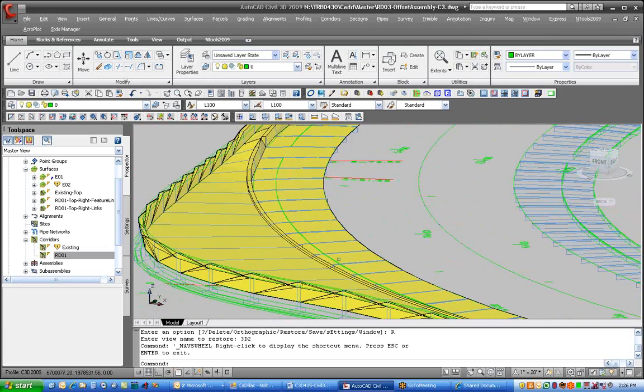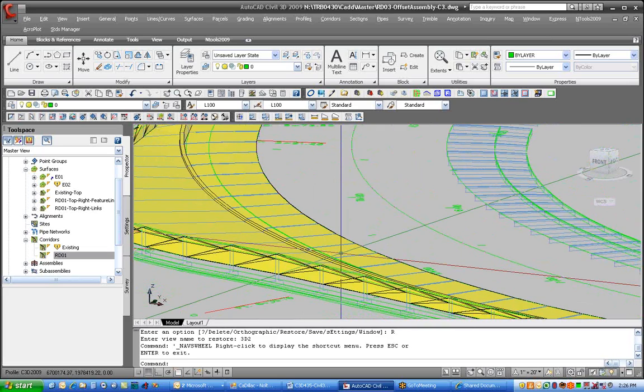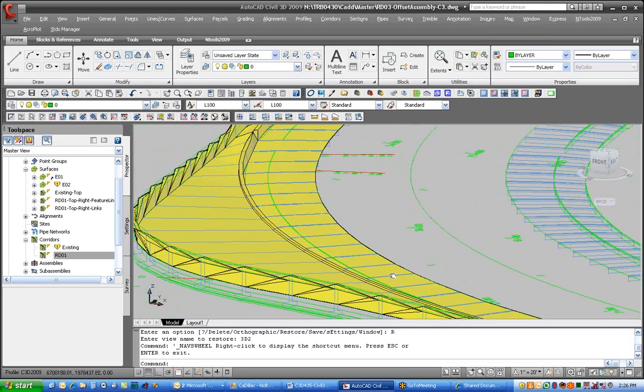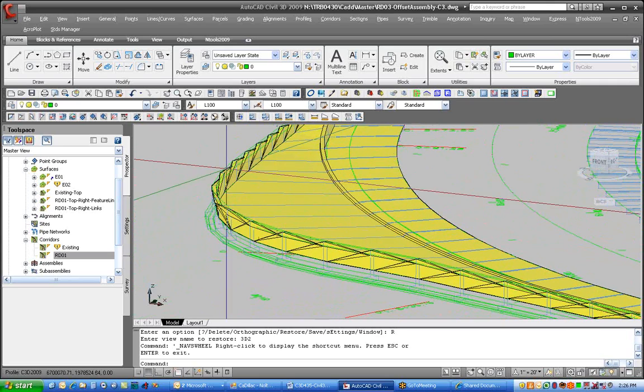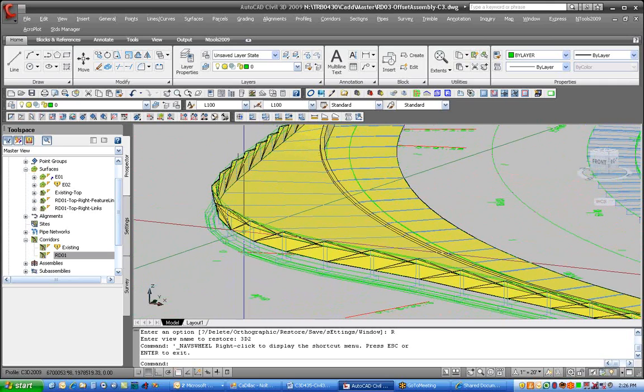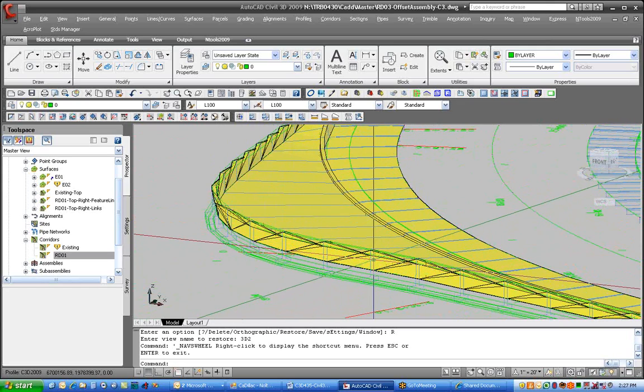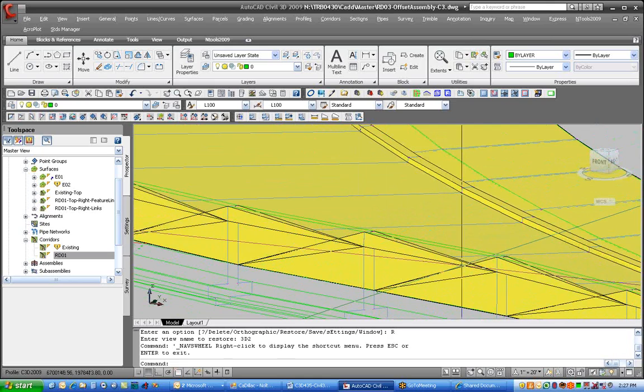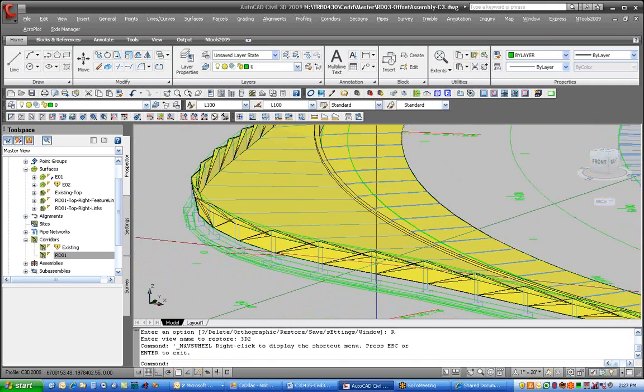Whereas now, here's the portion that was done using the link offset and elevation to control where things are, and you'll see the barricade and everything comes out real nice. But because these points back here aren't radial to the wall, off the top of the wall, it doesn't know where to triangulate, so it's actually triangulating down to these lower points here, so it's getting a little confused.